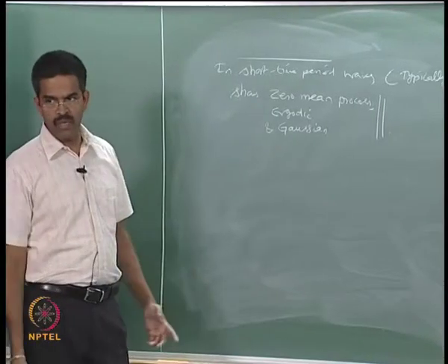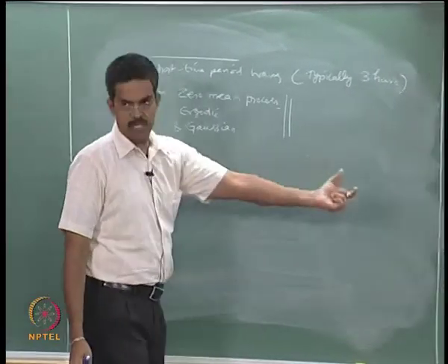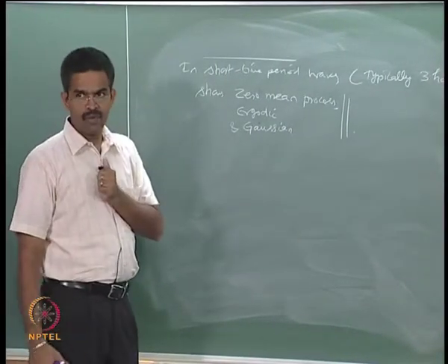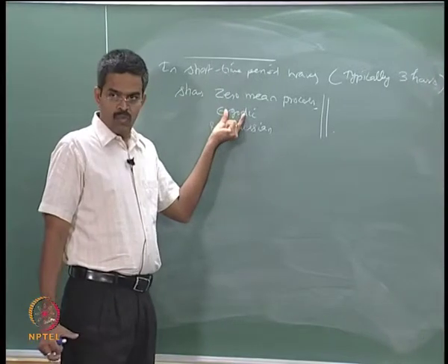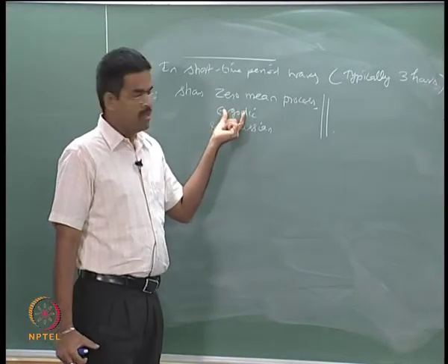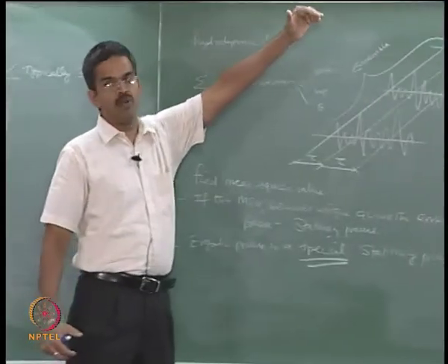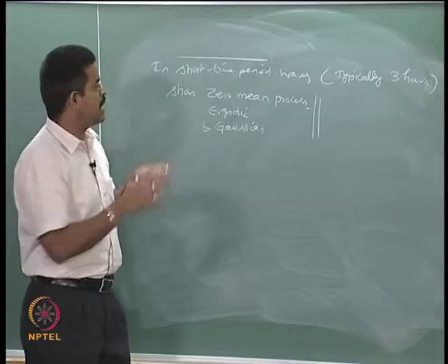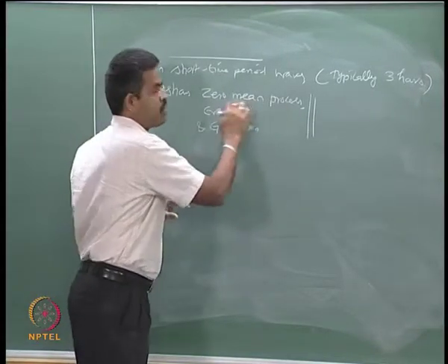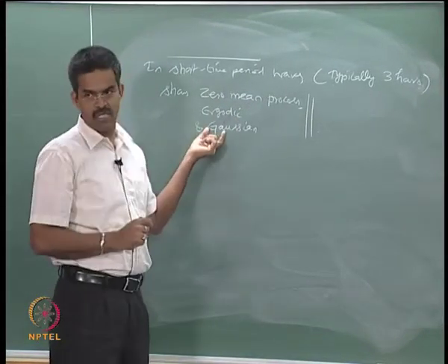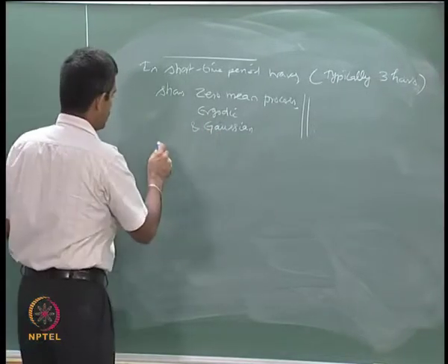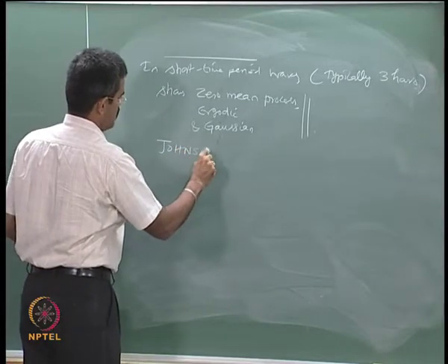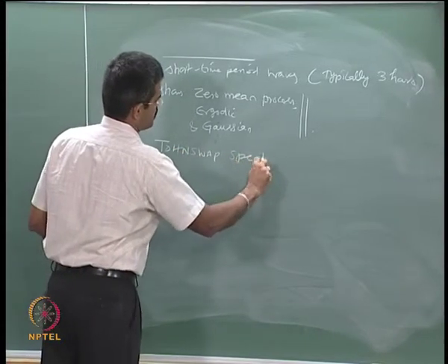Now to understand what we mean by ergodic, we are given this explanation. So I picked up a single sample which has a mean square value which is more or less matching with the mean square value of the whole stationary process on an ensemble, and that is the data I have with me, and generally that data has a zero mean and it is a Gaussian process. In such a case, to find out the forces, people use the JONSWAP spectrum.